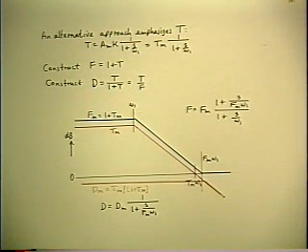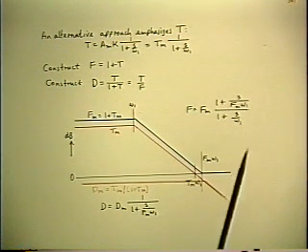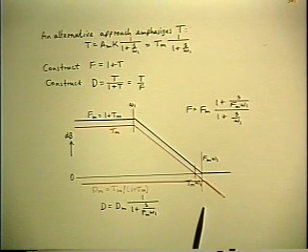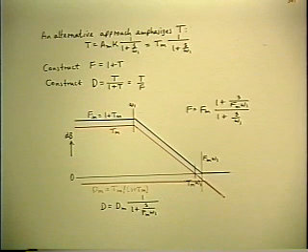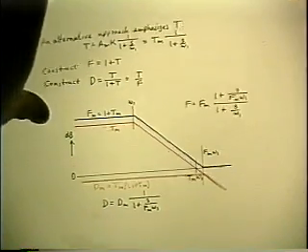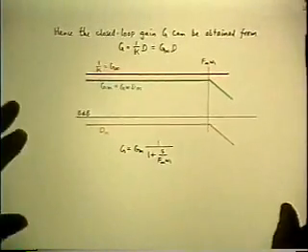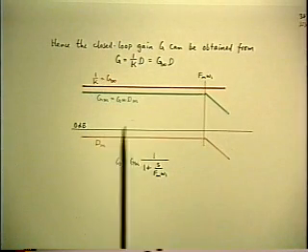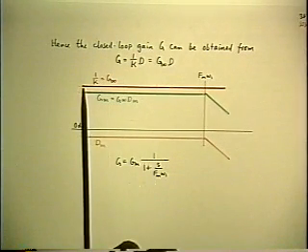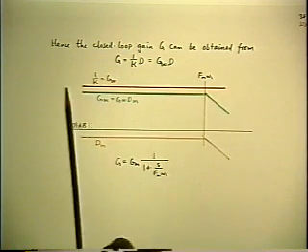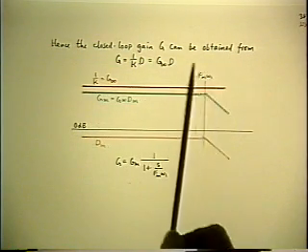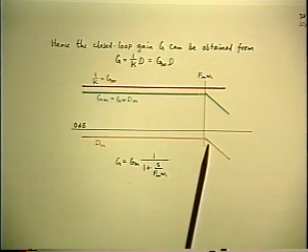So now we have both of the derived quantities. Starting with T, we have F and we have D. That's all we need now to find the final closed loop gain G, which is G infinity times D. The G infinity is the specification we started with, and in this example we've taken it to be flat with no frequency dependence. We have now found D, which is the orange line.